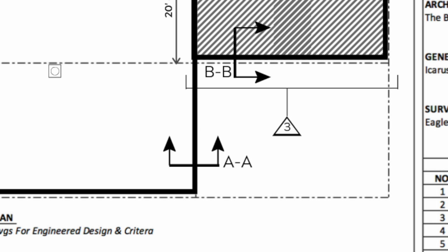Details are almost always close up and drawn from a specific perspective. When looking at a section cut symbol, the arrows depict which direction you're looking when viewing this detail. And as a general statement, details in construction drawings either give a close-up perspective, a different perspective, or a combination of the two. So back to these callouts labeled AA and BB.